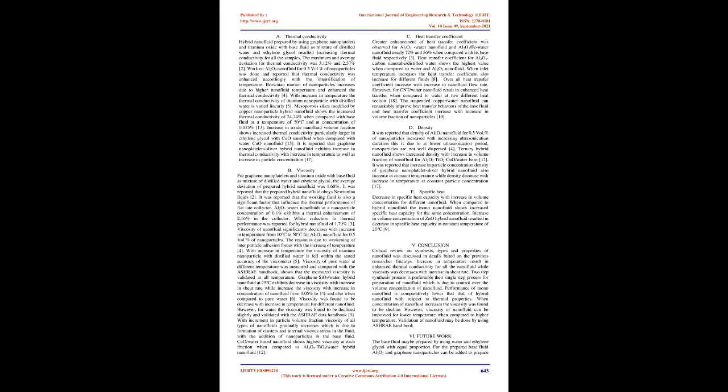2. Work on Al2O3 nanofluid for 0.5 volume percent of nanoparticles was done and it was reported that thermal conductivity was enhanced accordingly with the intensification of temperature. Brownian motion of nanoparticles increases due to higher nanofluid temperature and enhances the thermal conductivity. 4. With increase in temperature, the thermal conductivity of titanium nanoparticle with distilled water varied linearly. 5.